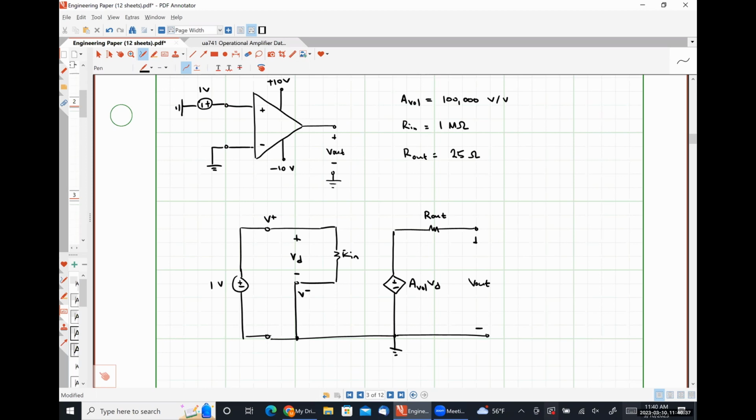For an op-amp circuit, we should never expect the output voltage to be more positive than the positive power supply voltage or more negative than the negative power supply voltage. This phenomenon is called saturation distortion. So effectively, in an open loop configuration like this, the output signal saturates to the positive supply voltage or the negative supply voltage for pretty much any signal that we can put on this thing. There are some cases where we're going to have amplification, and we'll talk about that here in just a moment.